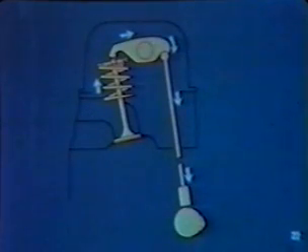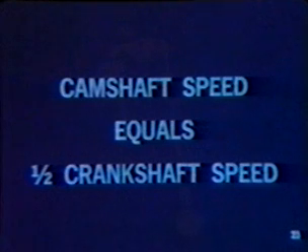The valve spring is compressed as the valve opens. Its force then pushes the valve closed again, and also pushes back through the valve train so that the lifter is forced to follow the surface of the cam. For proper timing, the camshaft is driven at exactly 1/2 of crankshaft speed, since it takes 2 revolutions of the crank to complete 1 cycle of combustion.